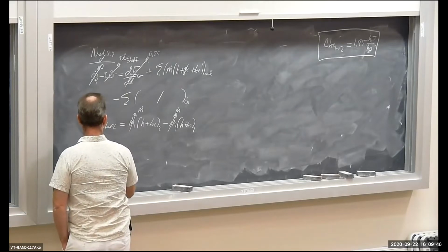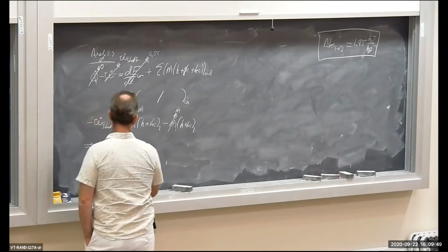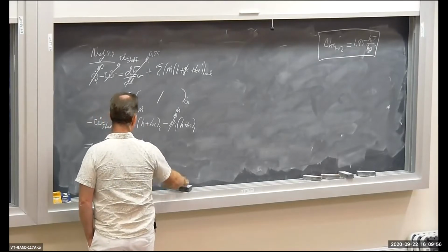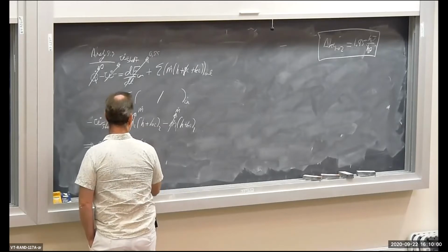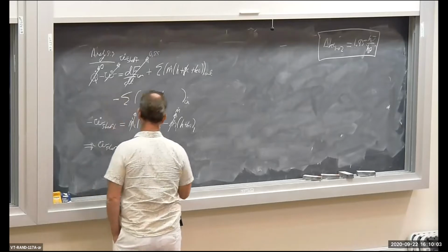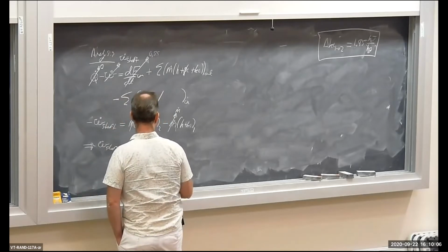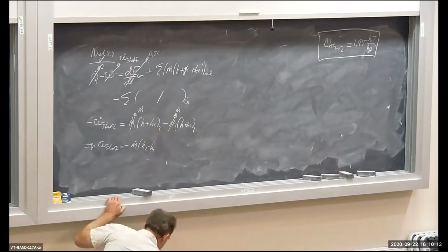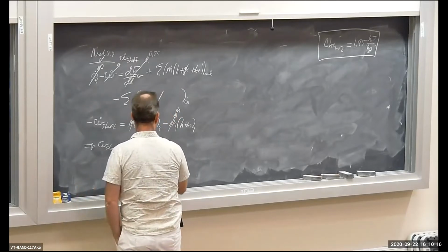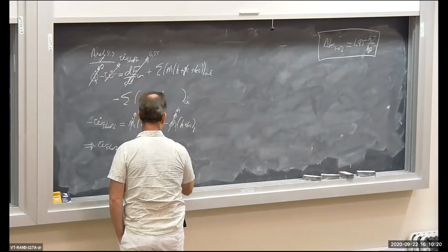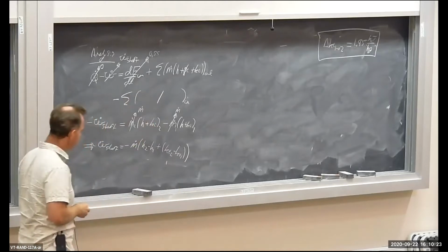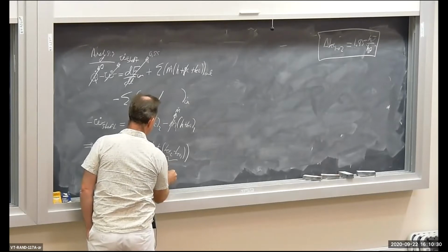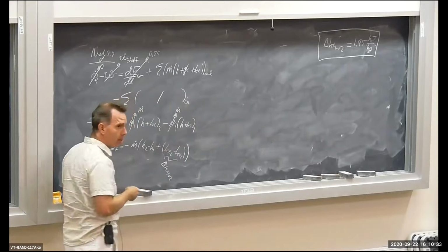W dot shaft, I'll distribute the negative sign, is negative M dot delta H. How about H2 minus H1 plus KE2 minus KE1, okay? Where this guy here is delta kinetic energy from 1 to 2. We've already calculated it.